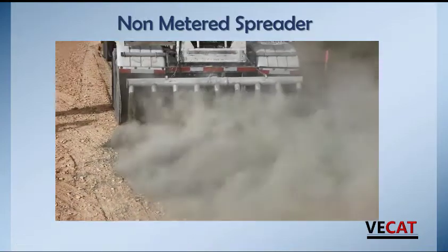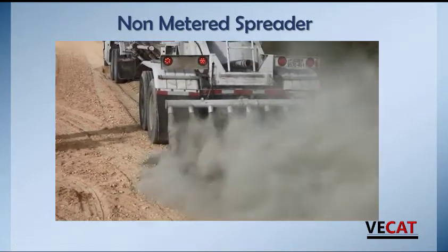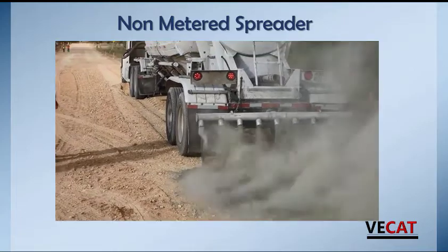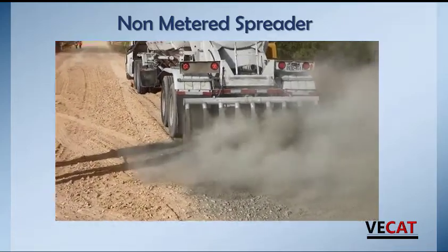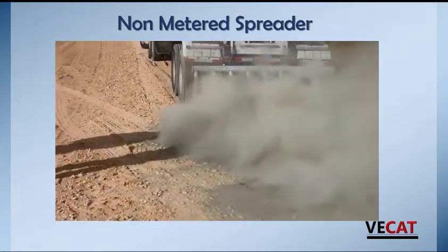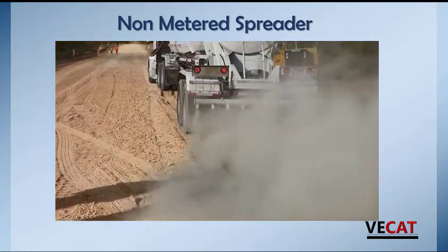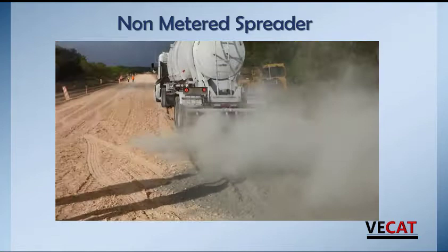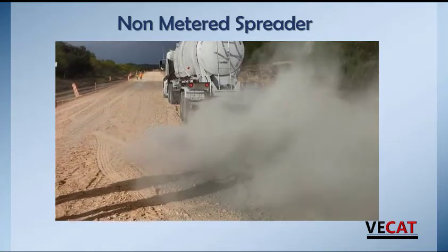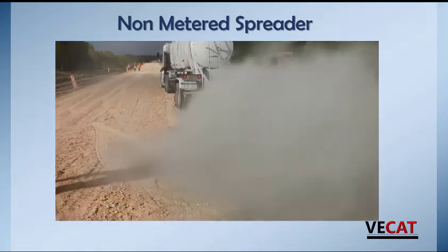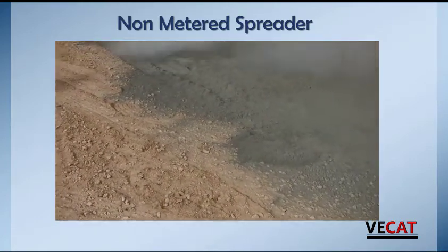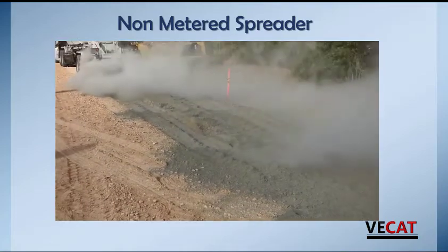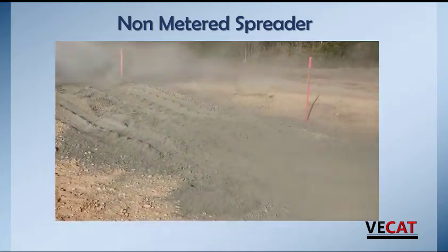All right, the first thing we've got is cement spreading. In this video, we've got a nice demonstration of how not to spread cement. There is absolutely no control coming out of the back of the truck. We have no idea how much cement we're spreading and where we're putting it. So in the very beginning, there was a large pile. And then as the driver pulls the truck forward, there's no spreading dependent on the movement of the truck.